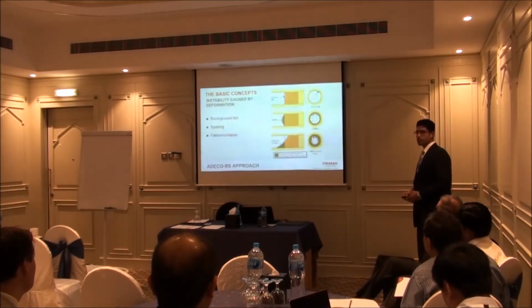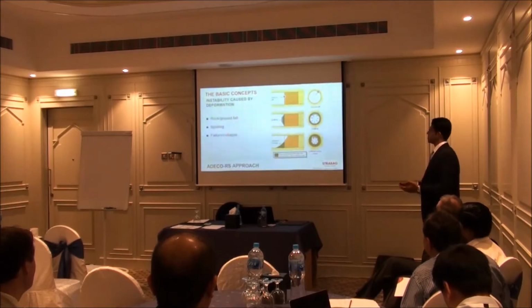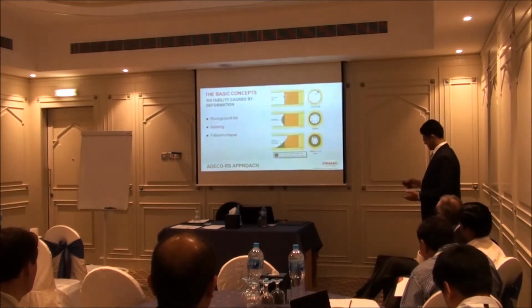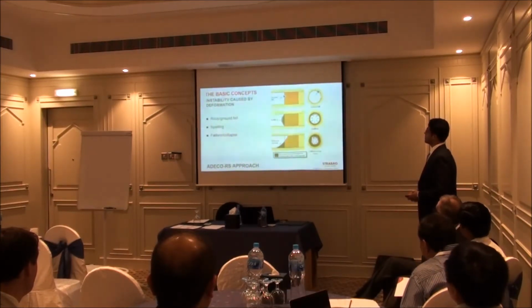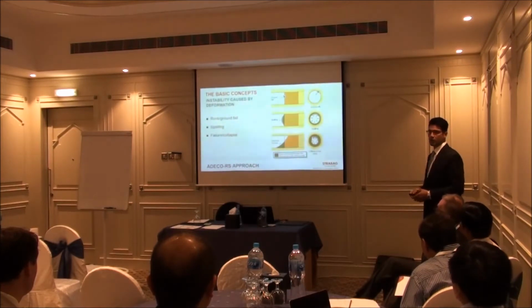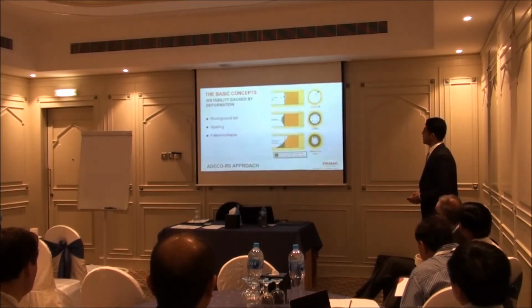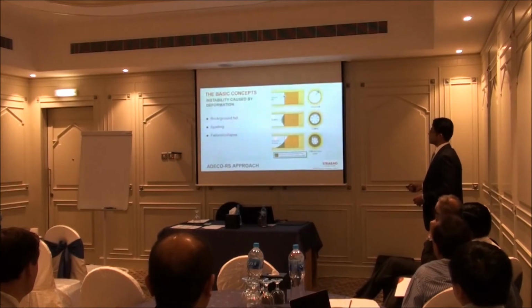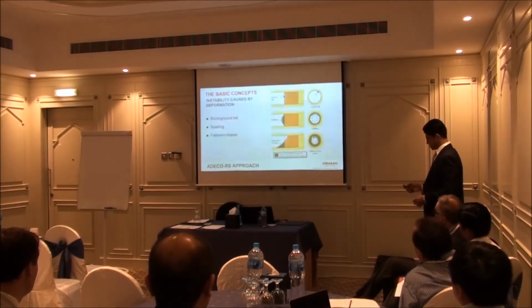So these three types of deformations can cause three types of instability behavior. First, in a stable condition, only some loose rock or loose ground can fall. In the second situation, failure of the face can happen, where spalling is happening at the face due to deformations. And the third is complete collapse of the cavity and the face.